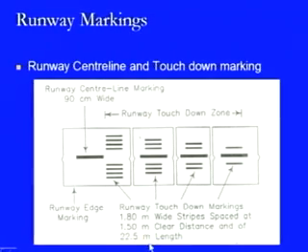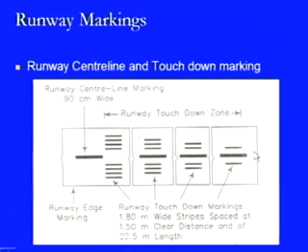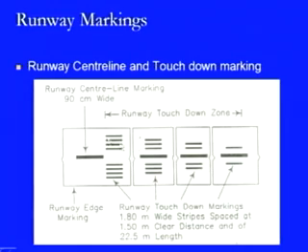The length of this remains 22.5 meters, the width remains 1.8 meter wide, and the gap between the markings is 1.5 meter clear. So, starting from these 4 lines to the single line which is located up to this particular distance, that is the runway touchdown zone. So, the aircraft will be coming and touching down at this location, and these strips are provided depending on the requirement. This number will be changing, there will be 4 strips and then 3 strips and so on.